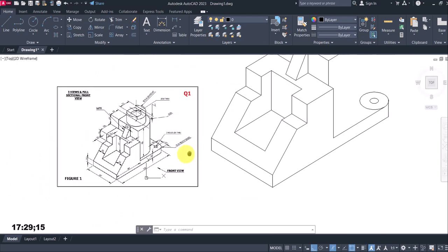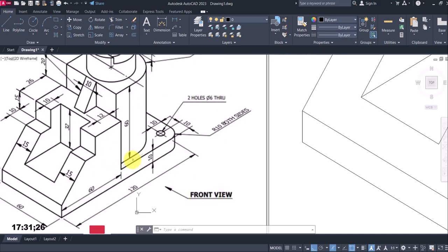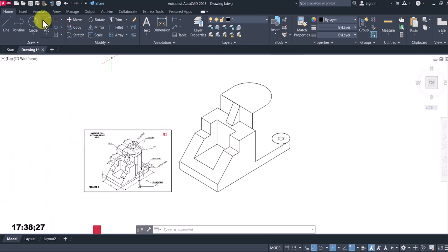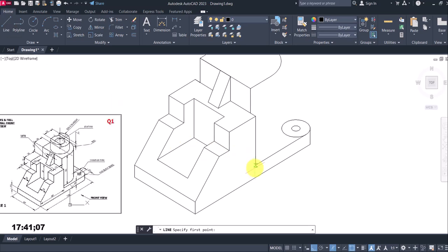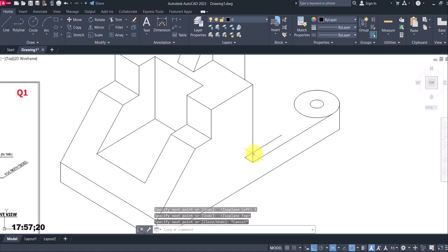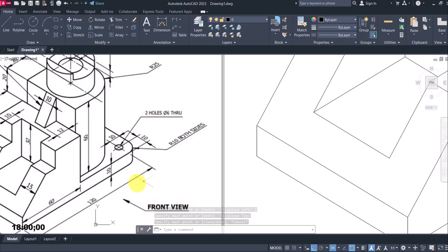I know there's a distance of 5, from the same calculation we did over here. So I'm going to step in that distance, 5. Press F5 to change my direction, 5. Then where that 5 intersects, I change my direction again. Where that 5 intersects this line will be where this point is going to be.